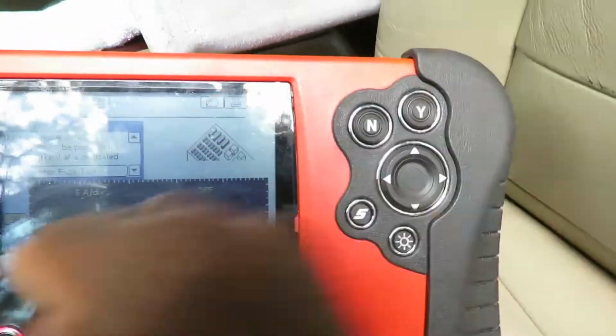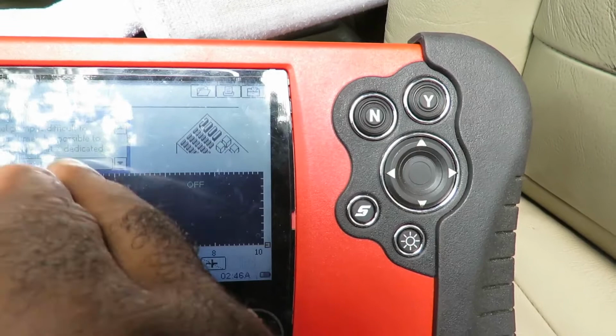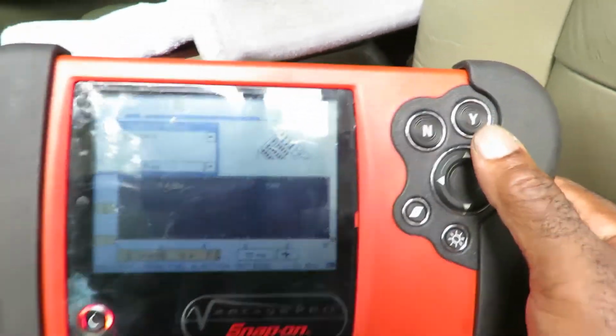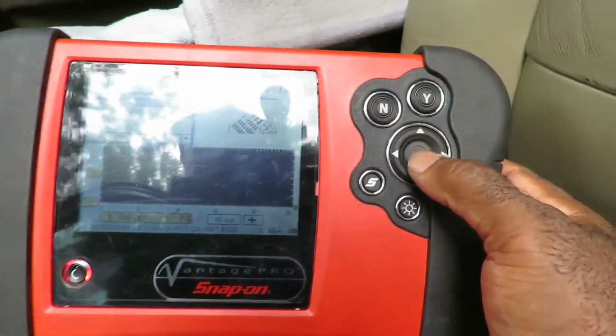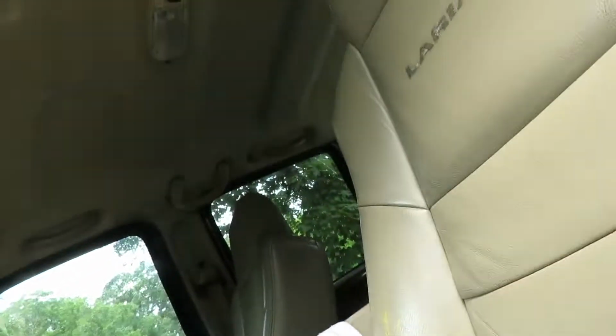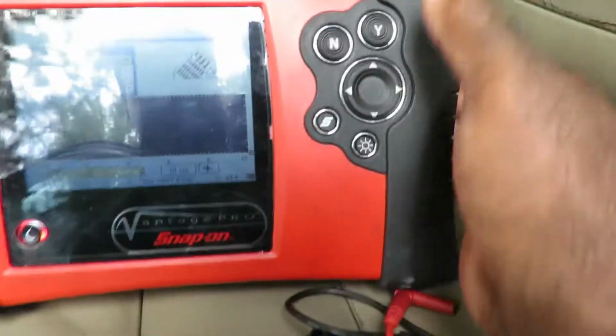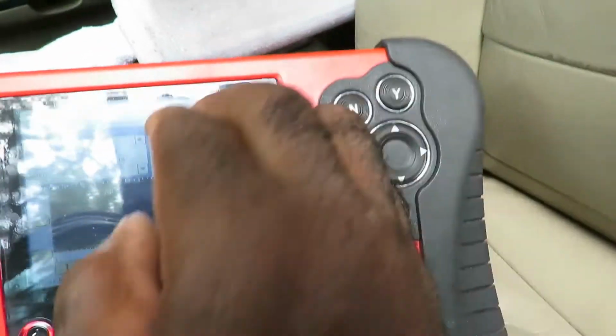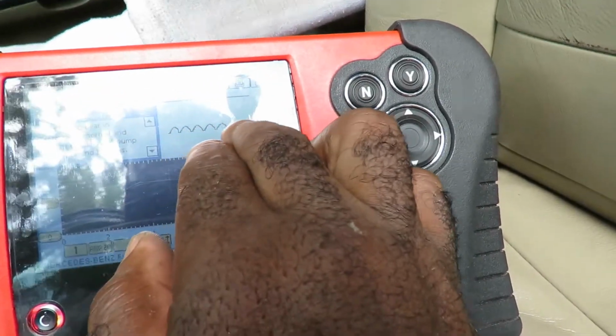Now if fuel pump is difficult to access, it may be possible to check current at a dedicated fuse if applicable. Now it does have a dedicated fuse, a 20 amp, and that's exactly what we're going to be testing it on. Make sure my mic is on. So now let's go back up here. Now when I start this vehicle up, my waveform pattern should look like this.